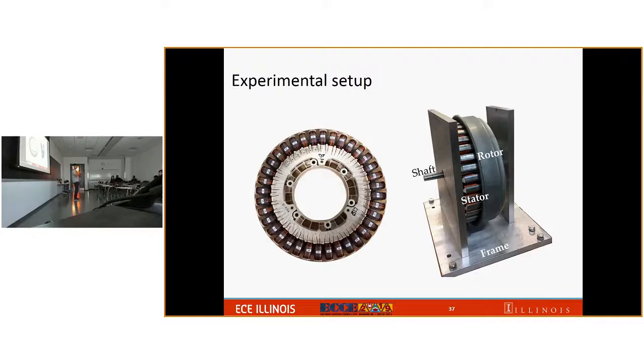But I can give you some initial thought at this point. So first, for example, we take from this figure. For one passive rectifier, you may have to series connect multiple teeth to power one passive rectifier or one active rectifier. Then you don't have to connect the teeth next to each other. You can distribute it along the air gap to have a more uniform thermal distribution.